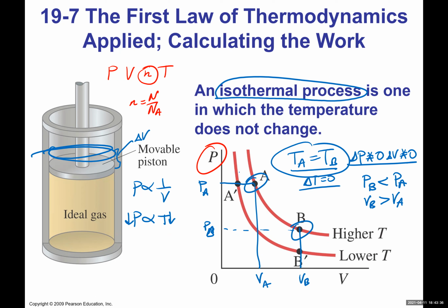Well, remember, this system is allowed to gain energy from the environment. Think of it like this: if I put some kind of hot plate over here and add energy at the same time while doing this process, I'm increasing the volume, which decreases the pressure, but I am also adding energy as heat, which then increases the temperature.